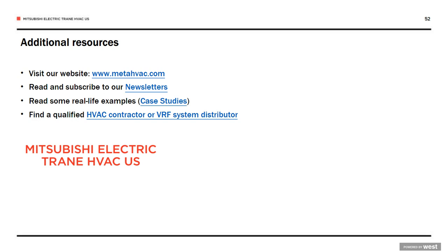Vic, when you're talking about building design, I'm assuming you probably see a hybrid of both. Yeah, definitely. We see a hybrid of both. But I will tell you, the question being, does it offset it? It offsets it a little bit, but in contrast, if we were to take the conventional system, your ductwork is going to be size X. With VRF, with DOAS, the ductwork will be 25% of X. So even though yes, you'll have that component, it's much, much smaller.